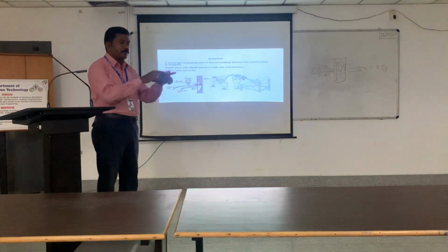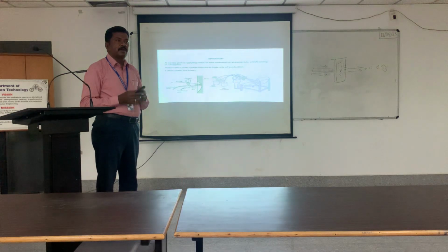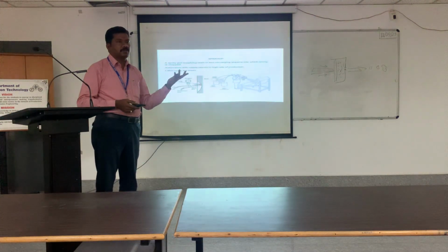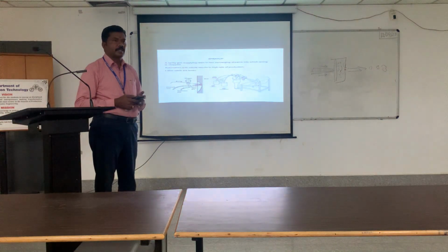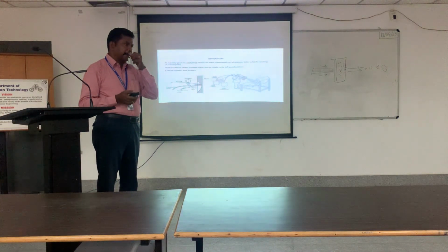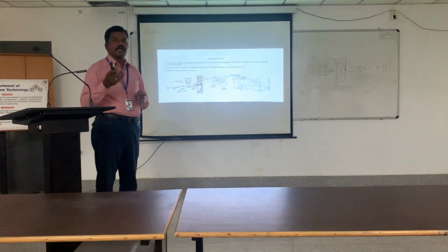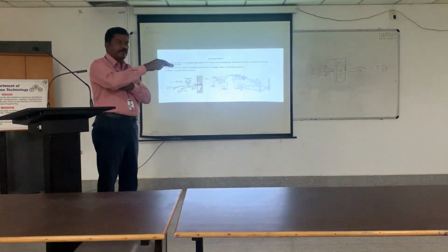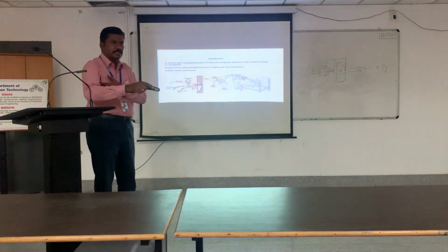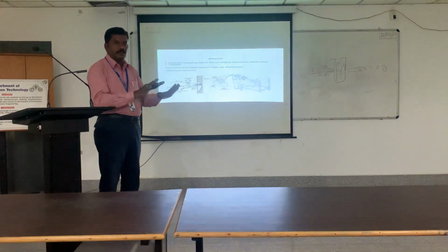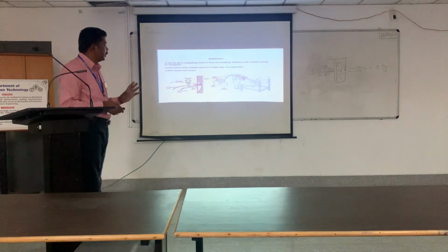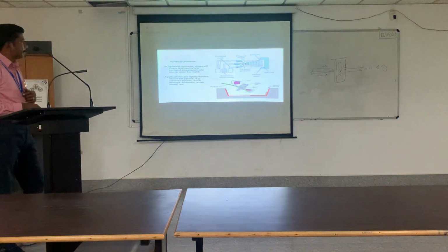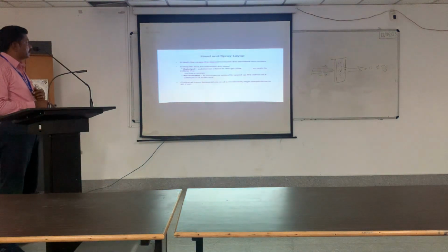If you are producing a component in large numbers, you can automate. If it is a job order, the cost is very high. So if the component number is very high, you can go for automated mechanisms. There the gun constantly moves from left to right, then the next layer, and the next layer likewise. Accordingly, you will get uniformity. Otherwise, it depends on the operator. This is the other diagram.